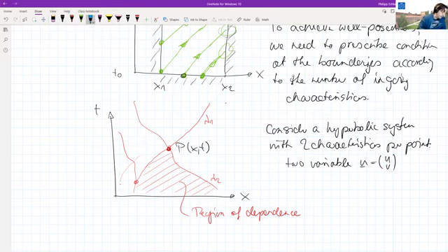In a similar way, you can also study what region in the domain is affected by the point P. Imagine that you go in and hit the flow, or change the flow, in this point P, and then you can wonder what region of the domain is actually feeling the fact that you have affected the flow. Of course, in a similar way, this would then be the region between the two characteristics. And this we can call the zone of influence of point P.